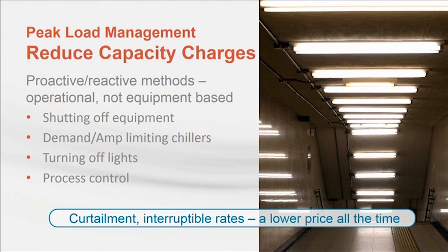The intelligence of when these events are going to take place typically comes from your energy supplier or a consultant like Trane. The peaks can be identified by monitoring weather patterns, generator dispatch, and other local market factors. Generally speaking, though, the events are going to happen on the hottest afternoons in the population centers of the grid operators. Historically, the coincidental peak demands take place between 3 and 6 p.m. because there is a collision of industrial, commercial, and residential demand.